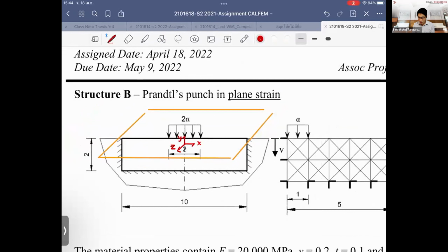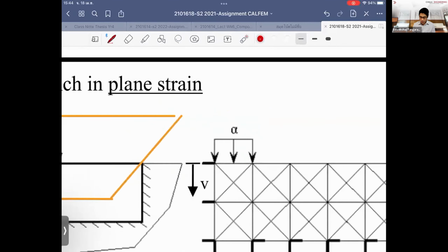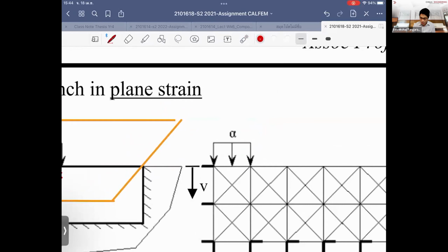If the problem has the depth going to infinity, then the strain in the perpendicular direction, the strain in this direction here, tends to be very small, because this goes to infinite depth. The thickness is so deep. And we call this the plane strain. The condition we have here, looking at the strain by itself, is that the strain in the perpendicular direction, the strain in the z direction, is equal to 0. We have the shear strain in the perpendicular direction as well, equal to 0.